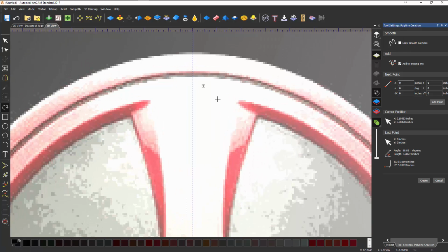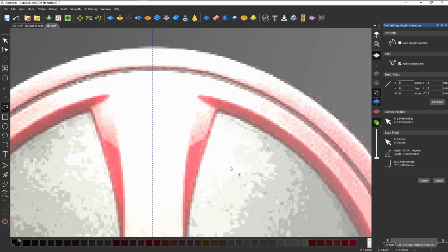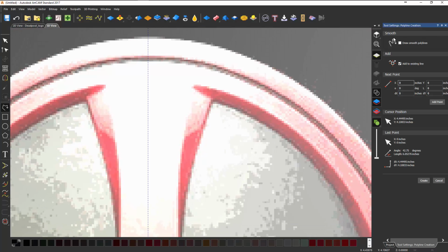Okay, and in this, I'm going to use a series of smooth curves and lines to build up my design, which is going to give me some sharp corners in spots and then curves where needed. Now, instead of coming up to my Draw Smooth Polylines tool each time I'm changing this, I'm actually going to use a shortcut key on my keyboard, which is the letter S. And we can see if I click on S, next to my cursor appears an S symbol representing smooth, and if I click it again, the S disappears.